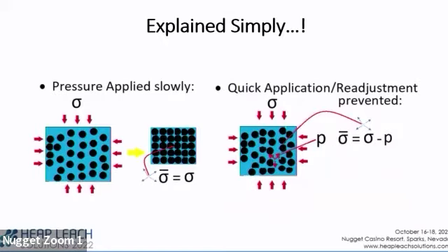What we can have is a problem where you've got a relatively loose material, and I'm going to call it soil because this is soil mechanics, but it's spent ore or tailings, in a looser state so that when you load it, it compresses, or what we call for liquefaction purposes, contracts. It's a contractive material. And if it's saturated or nearly saturated, it tries to push the water out of the way. And if the permeability is low enough, the water can't get out of the way, and you pressurize the water.